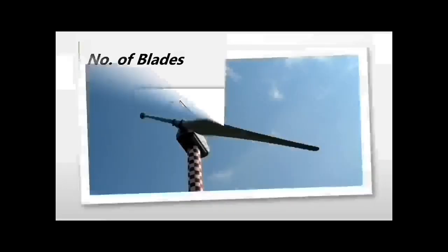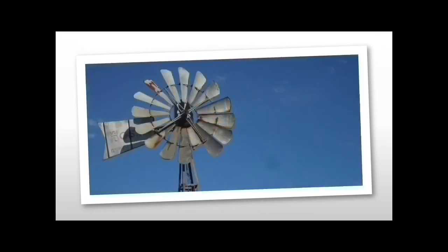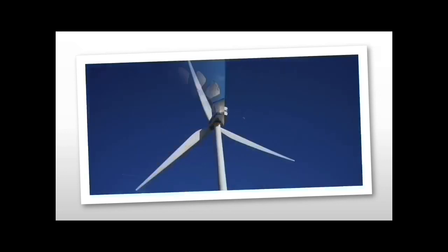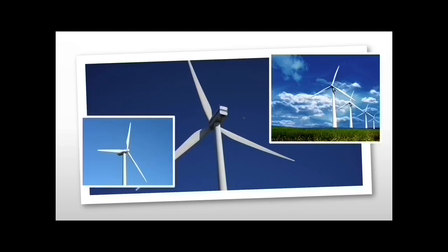Aerodynamically, a one-bladed turbine is the most efficient. However, this requires a counterweight for balance and to address stability issues. Any number of blades greater than 3 would generate the necessary wind resistance that will consequently make the turbine less efficient due to interference between the blades. 3-bladed turbines are considered to be the best compromise between energy yield, stability, and durability for real-life wind turbines.